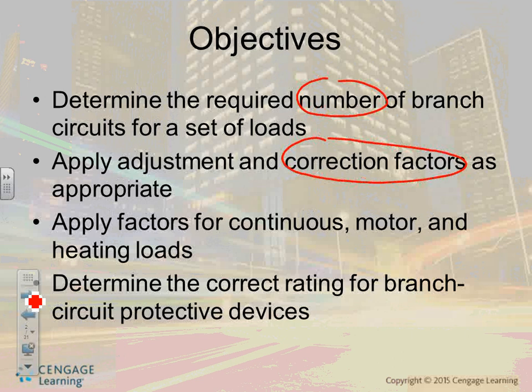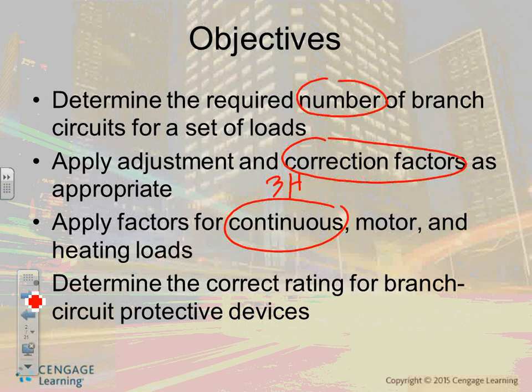Okay, we talked about this one in the past, guys. Continuous load. Anybody say what continuous load is? How many hours? Thank you. And what do you do with the load if it's continuous? 1.25. You up it 25% for safety. So if the load is 10 amps, you put 25% on it, it becomes 12.5 amps, and you size the conductor. Why? Safety.